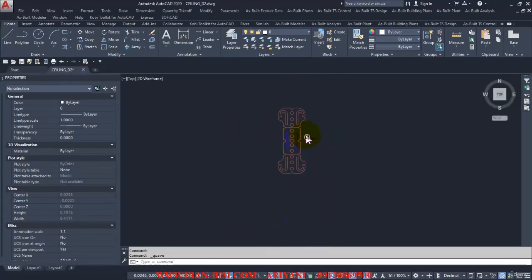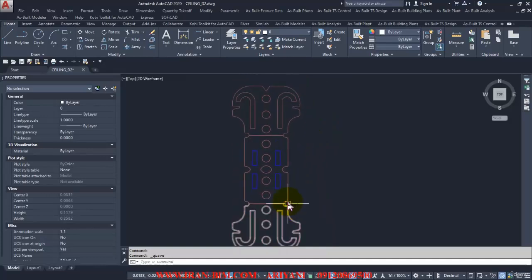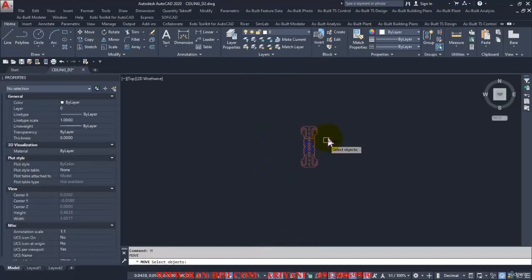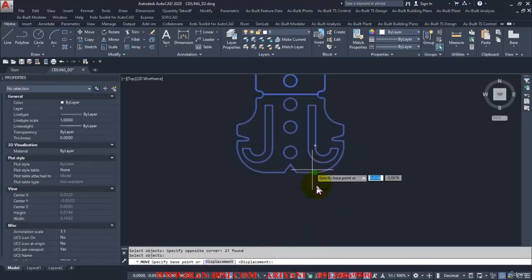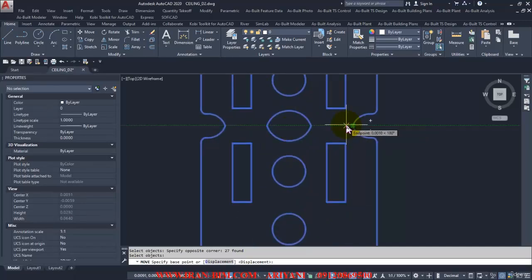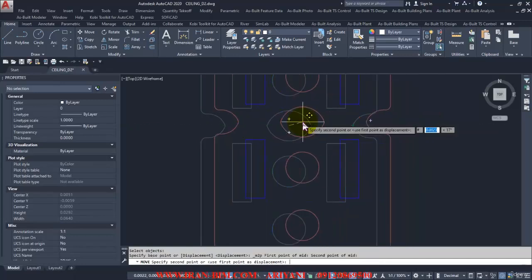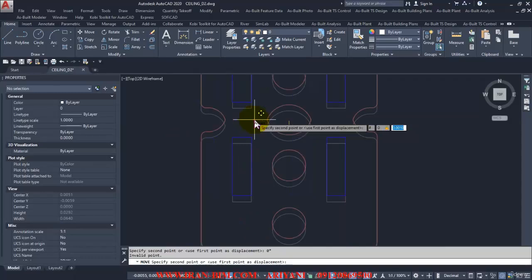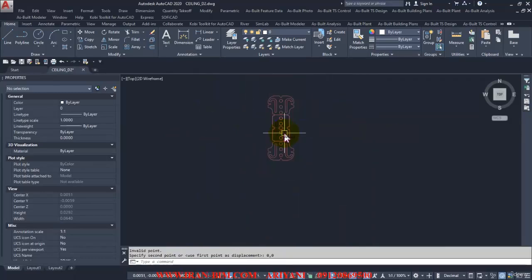After saying that, we go here and select the plan that we have here. Then we zoom in on it and see what we have. Alright, we'll select this point and then right click on it, click on mid between 2 points, and then set the points in here and here. So select the middle part and put it under 0 and 0. Then shift plus square, 0 and 0 here, and then enter.